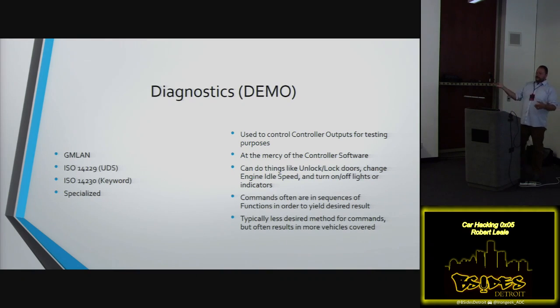If you want to turn the windshield wipers on from the CAN bus from the diagnostic port, just send the request. And what's crazy is when the OEMs finally start locking us out of the normal messages that are going to turn the controller on, they're going to have a real difficulty locking this part out, right? I mean, it's going to be a challenge because they need their techs to also be able to do these diagnostic controls as well. So it's a big challenge they have to weigh the benefits. There's always a way. Essentially this is a feature that they've added on purpose, and they want their techs to be able to plug into that diagnostic connector and send these controls.